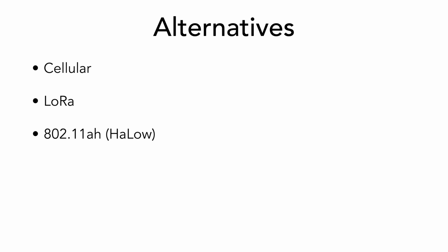We could have gone with LoRa. We'll have a whole lecture dedicated to LoRa, and some of you are doing this in your projects. LoRa is a long-range wireless protocol. We've mentioned it throughout the semester. That seems like a good fit. But you need another radio. You need different hardware, and then you also need a gateway associated with it. So where do you put this gateway? You could put it in the home. You could put it in the neighborhood. But it's not that clean of a solution. It costs a lot of extra money.